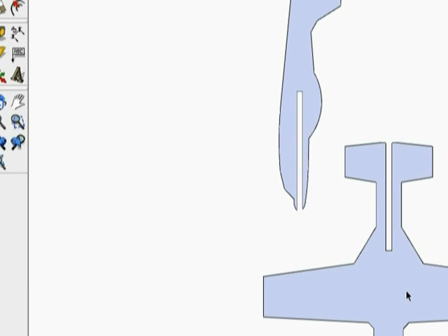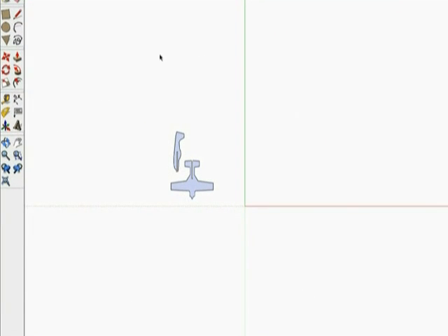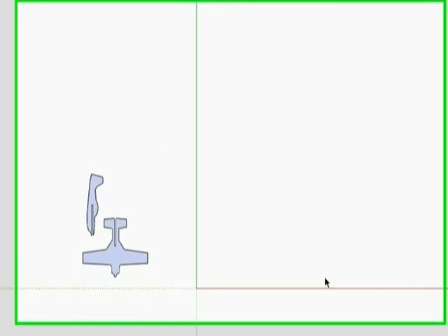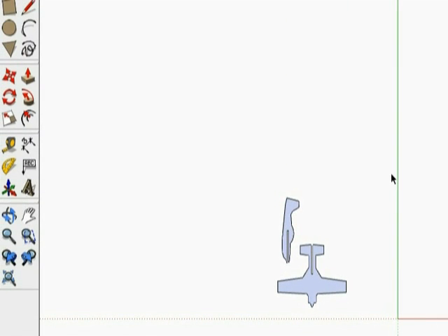But what we're going to do here, again, I'm not going to go heavy into the design, but I'm going to show you how to take these models and assemble a 3D representation so that you can make certain that everything fits properly from your 2-dimensional parts. Now you may notice we've got a quadrant here. And over here, this is the quadrant that your flat printer will be cutting in all the time. These represent your positive movement of X and positive movement of Y.